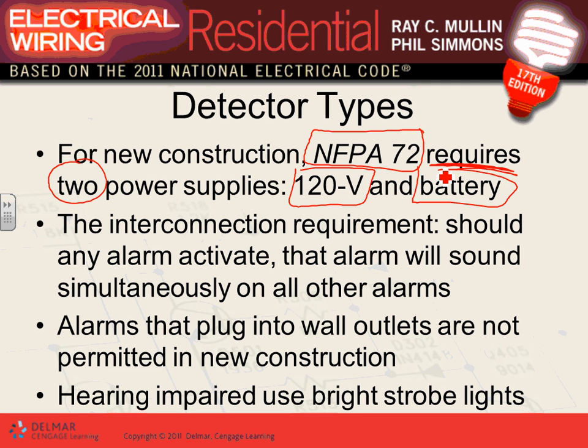One of them has to be powered by 120, and it has to have batteries. That's new construction. Everybody understand that one? In the dwelling project that we have right now, you must provide, like we hardwired it yesterday, I told you, and they will come also with batteries. Very, very important. The second requirement, this is requirement number 1.